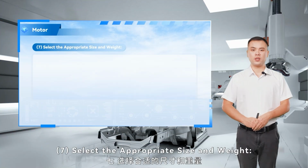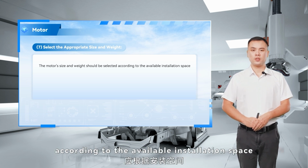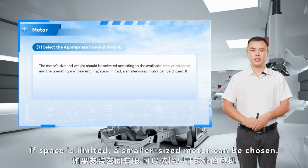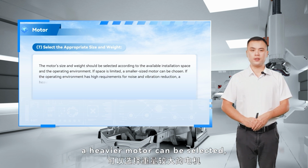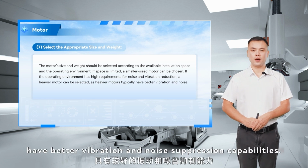7. Select the appropriate size and weight. The motor size and weight should be selected according to the available installation space in the operating environment. If space is limited, a smaller sized motor can be chosen. If the operating environment has high requirements for noise and vibration reduction, a heavier motor can be selected, as heavier motors typically have better vibration and noise suppression capabilities.